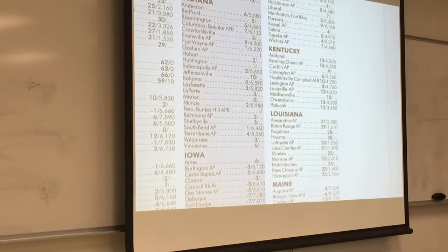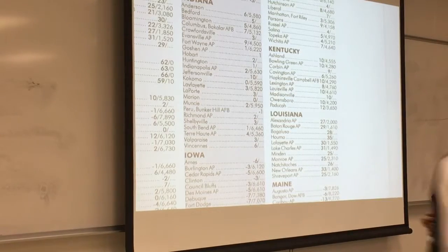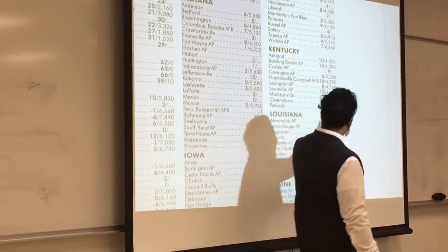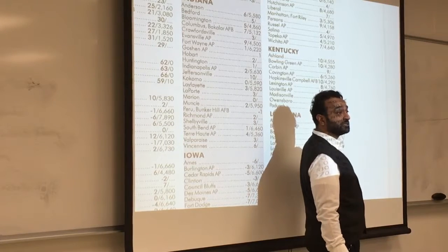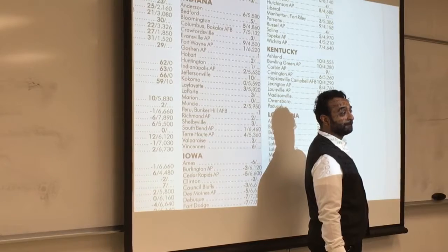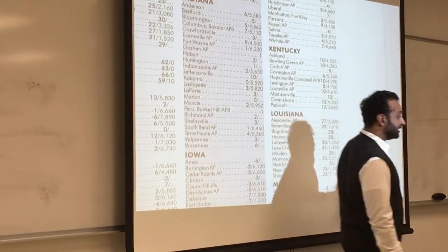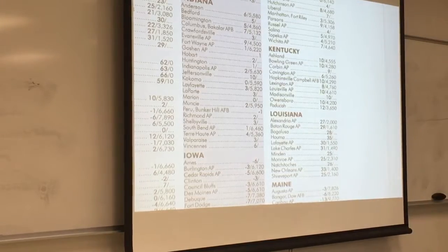So, if you want to estimate how much fuel you need, why do we need to do that? So I know how big of a tank I need to buy. This will help me know how much fuel I need. This is the number of degrees for the entire year I'm going to heat the house. This is valuable data: how many days and hours I need to heat the house. It's given to you for each city. So I take that number